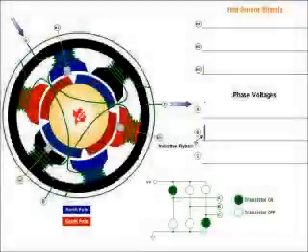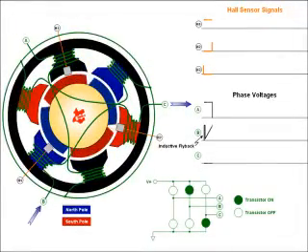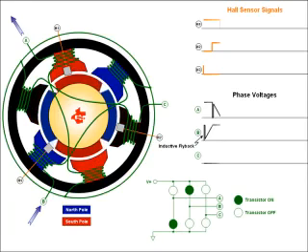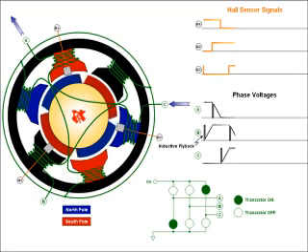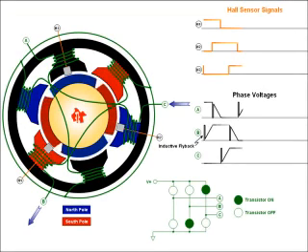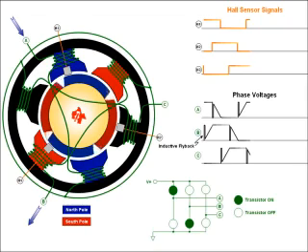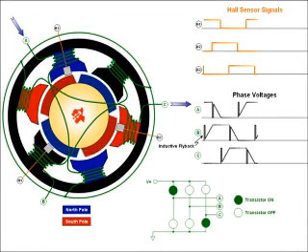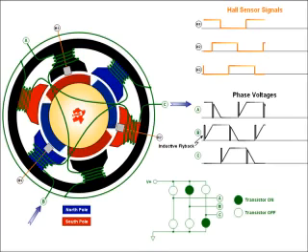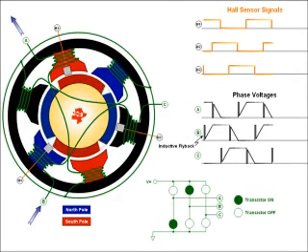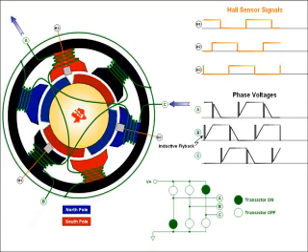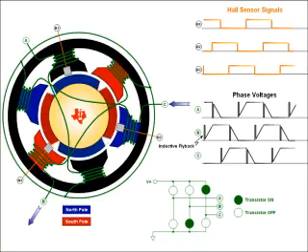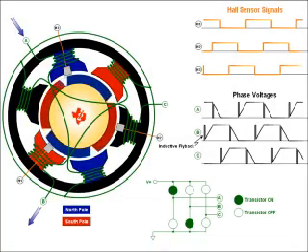The brushless DC motor has only two basic parts, the rotor and the stator. The rotor is the rotating part and has the rotor magnet, whereas the stator is the stationary part and contains the stator winding. In a brushless DC motor, permanent magnets are attached to the rotor and the electromagnets are in the stator. High power transistors are used to activate the electromagnets for the shaft to turn. The controller performs power distribution by using a solid state circuit.